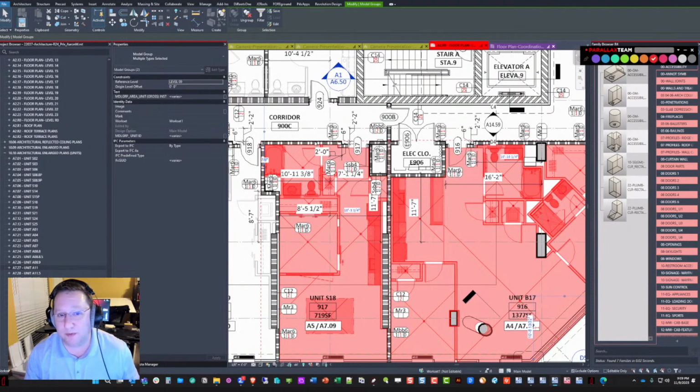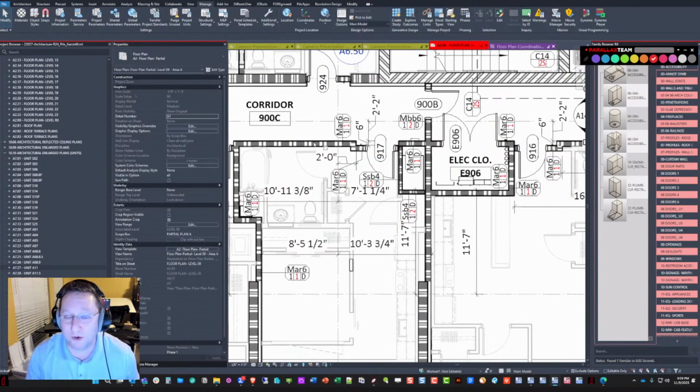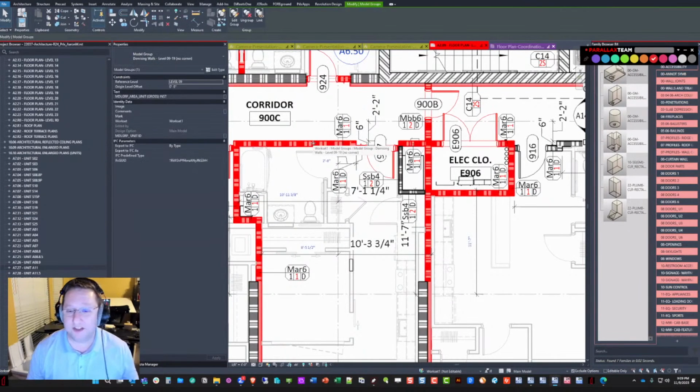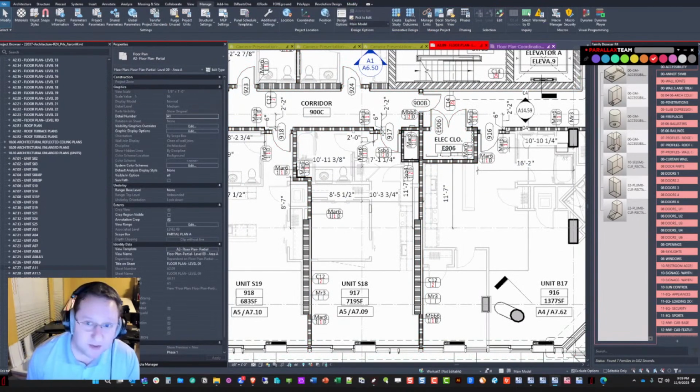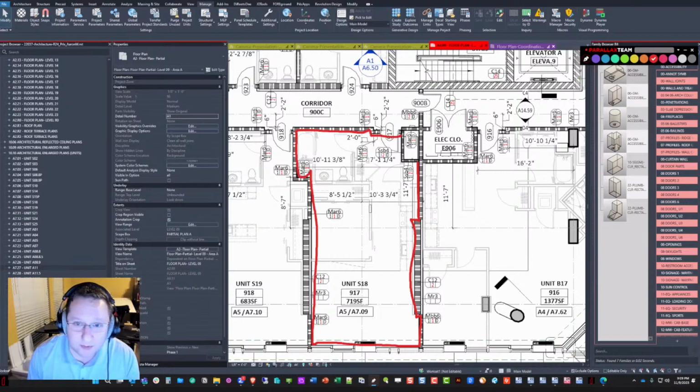Now, for teams that like to be brave, sometimes we do group the corridor elements as well, especially when they're similar from level to level, because then you don't have to deal with all the changes of the corridor and everything. So folks always ask me then, well, if the demising walls aren't in the group, how in the unit cloud do I make sure this is exactly where the unit ends? Because I have to put fake demising walls in the unit cloud, right? And in Revit, what's the first thing everybody always jumps to? Construction lines. Probably reference planes or hatches or detail items, filled regions, something like that.